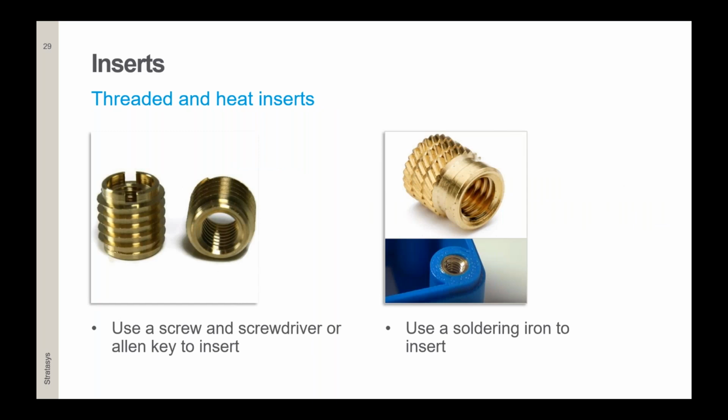Apart from nuts, we can use different styles of inserts after printing our model. For example, a threaded insert on the left. Inserting it post-print is something similar to screwing a wood screw into a plank. Another option is using heat inserts, which is on the right picture. It is easier to insert, but requires something like a soldering iron or a similar tool to heat the insert.